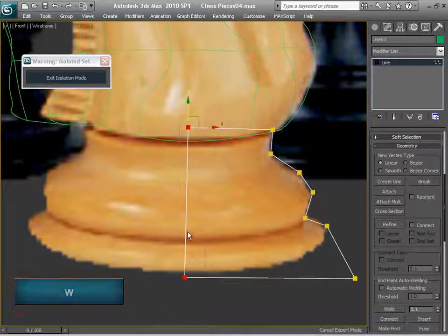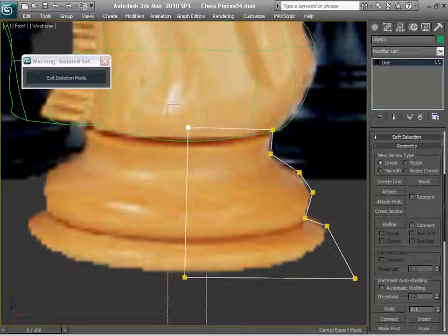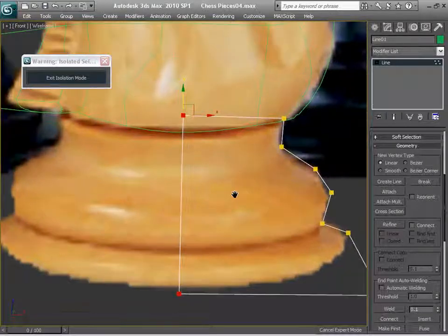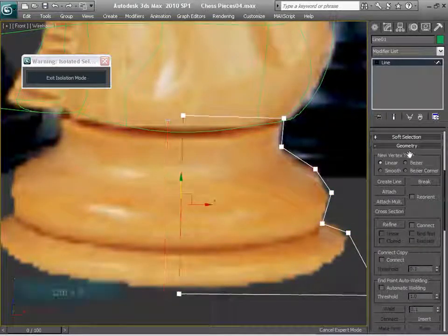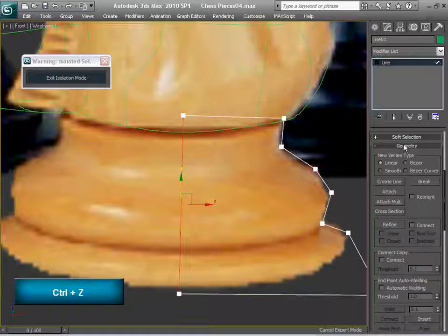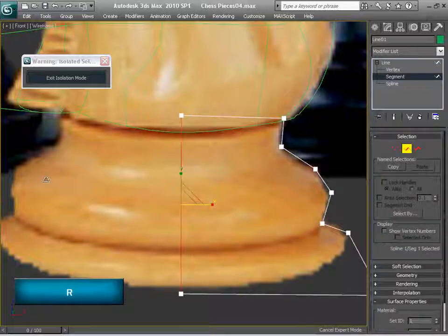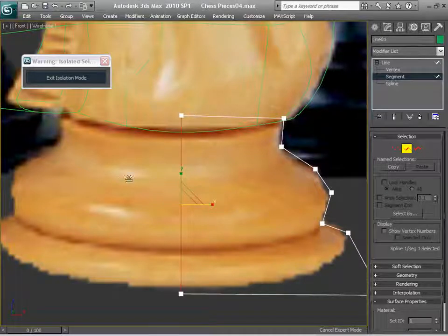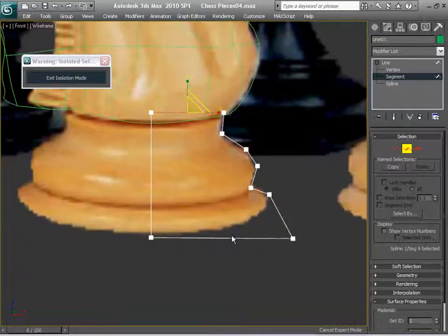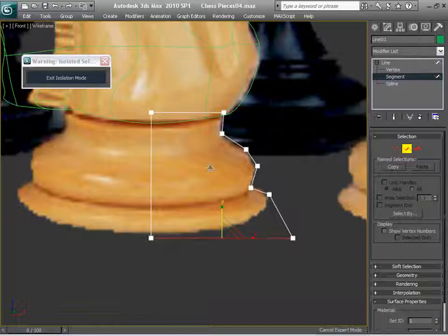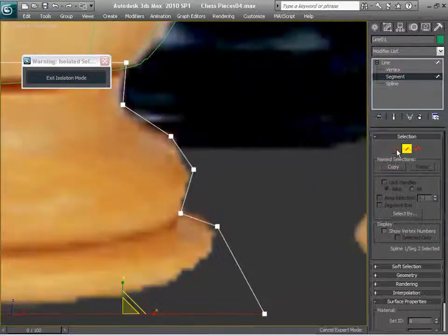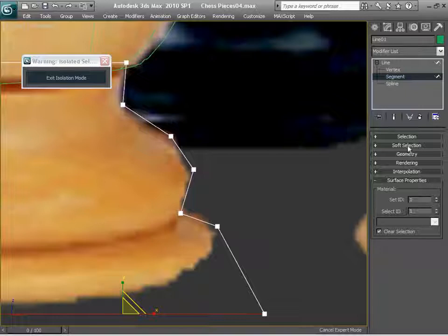And right now, as I created this without the snap tool, I'm gonna enter into the segment mode, and I'm gonna select the scale tool. When you move into the X axis, in this case, I'm gonna line those two vertices up so it is a straight line, as well as this one here. In this case, I'm gonna use the Y axis, and that way I'm making sure that those are straight lines.